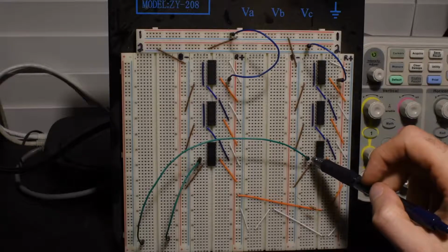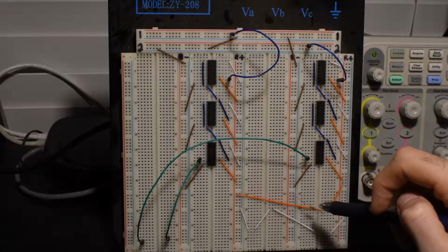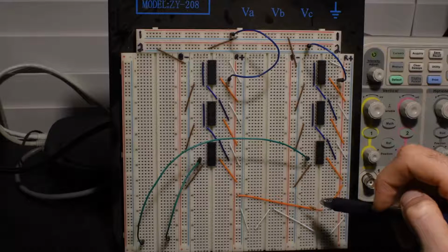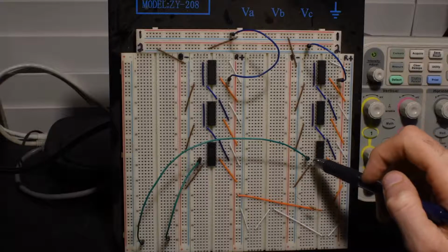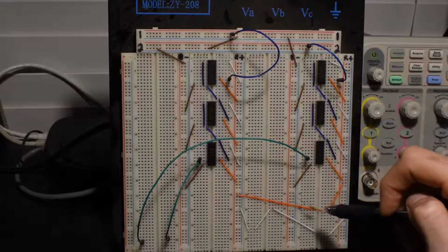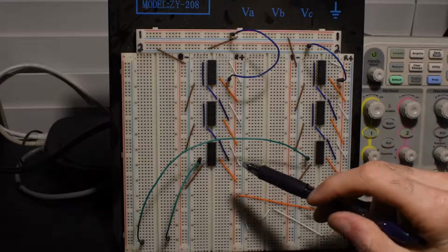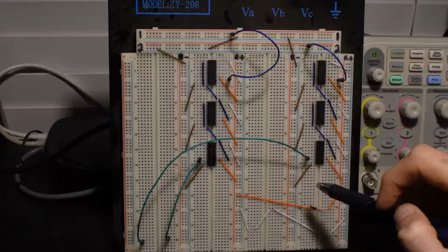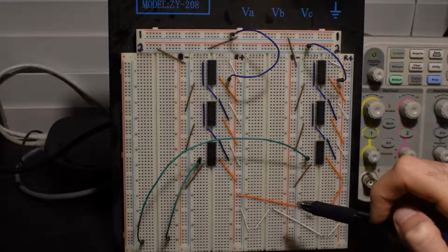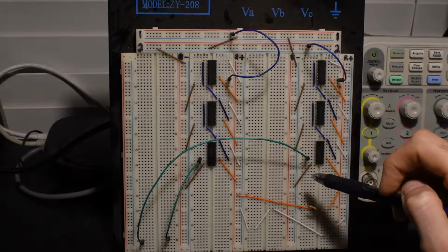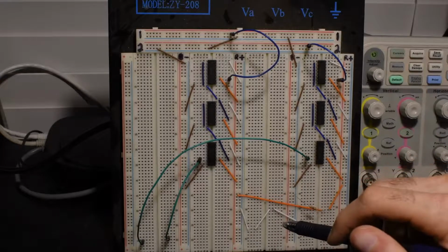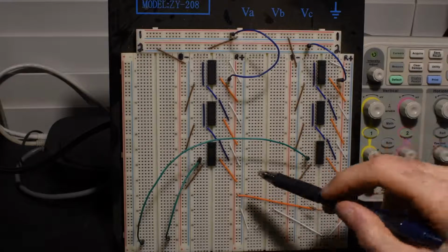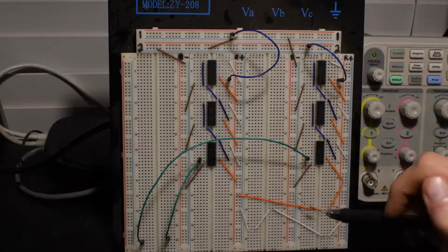So these green wires are what are going to come out and actually connect to the oscilloscope to do that comparison. Every 13.4 seconds we'll get a rising signal on both of these chains, and it'll be offset by some pretty small length of time. That length of time, and how it changes from one cycle to the next, will tell us how the phase is varying between the two chains.